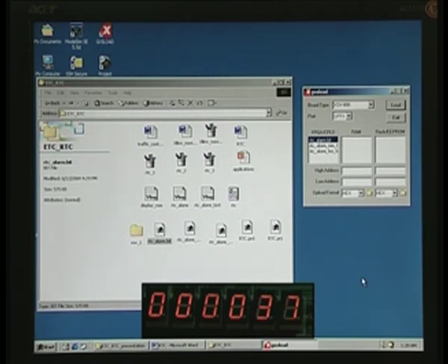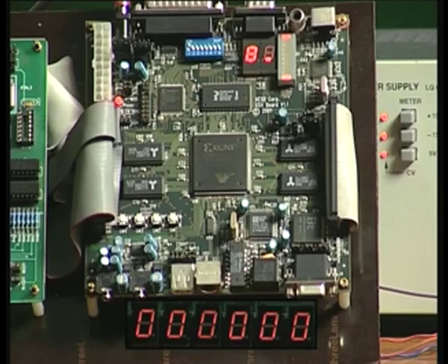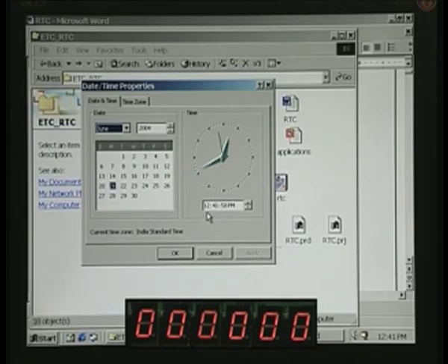Now let us say we want to set it to the desired time, so I will first invoke the time here. We will first set the hours setting here, and it is right here. We have a DIP switch here, and down we have 4 push button switches. We need to use the left push button switch in order to do the setting. So, we will now do the setting as per the system clock, which you see right on the computer, and it is now 12:41, 12:42. We will set it for 12:43. Now hours will be set.